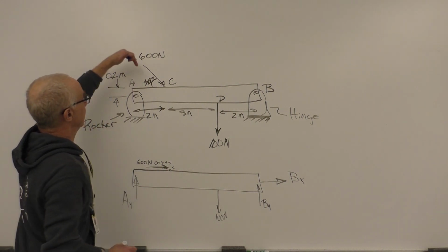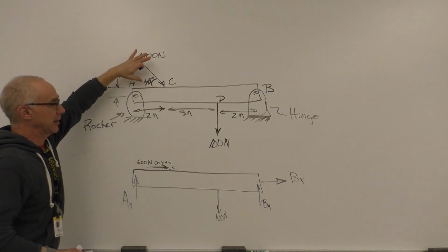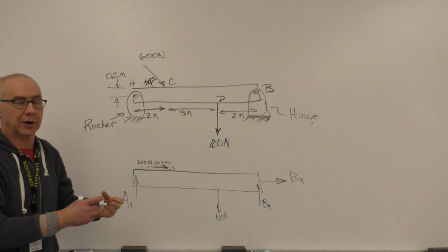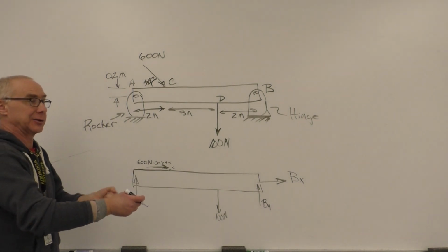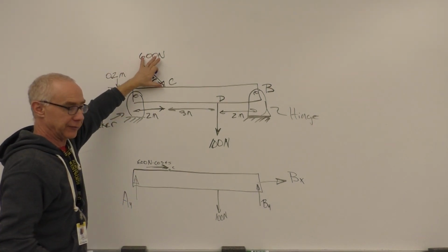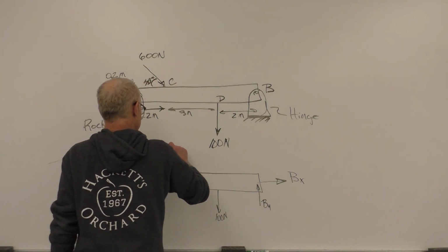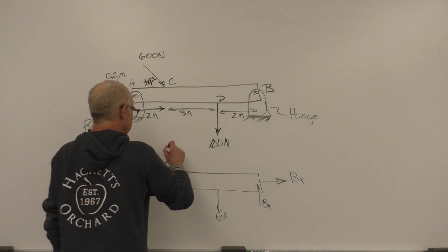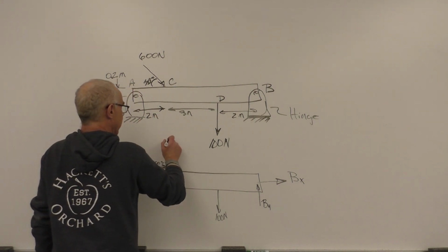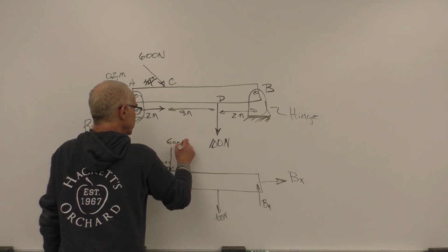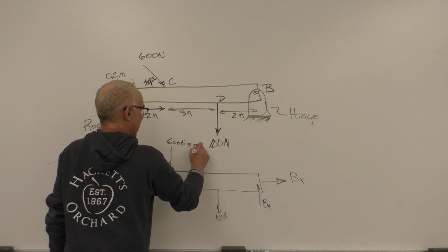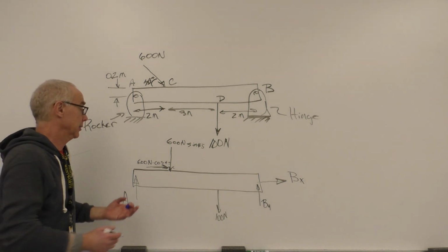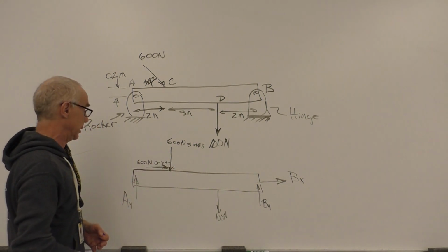And then the y component. Because we've drawn this, you see that I'm not necessarily drawing it in the positive x direction or positive y direction. I'm following the convention from the problem itself. So in this case, we're going to have a vertical force. If this one's 600 newtons cos 45, the horizontal, then the vertical will be 600 newtons times sine 45. And you may not know this, sine 45 and cos 45 are the same value. So in fact, the x and y components of this will be the same.